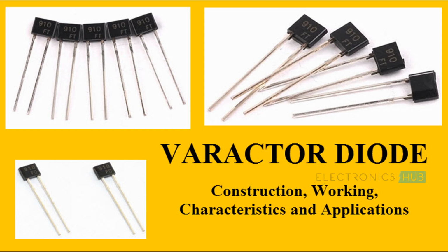Key features and applications of Varactor diodes include voltage-controlled capacitance, which refers to the property of certain electronic devices, particularly Varactor diodes, where the capacitance can be modulated or controlled by applying an external voltage. This phenomenon is utilized in various applications, especially in radio frequency (RF) and microwave circuits, to achieve voltage-tunable or voltage-variable capacitance.